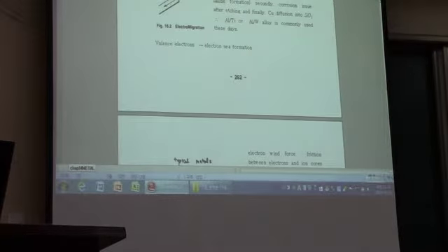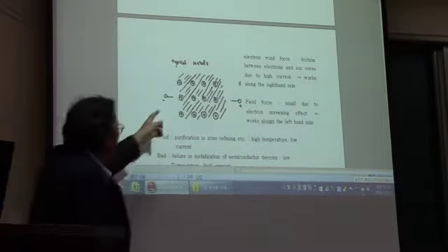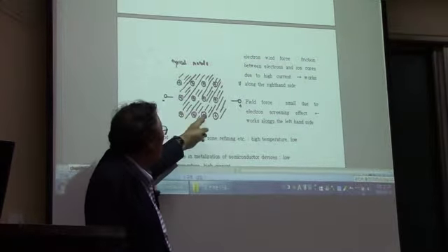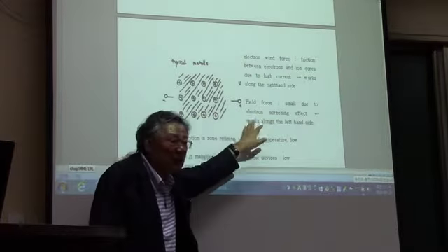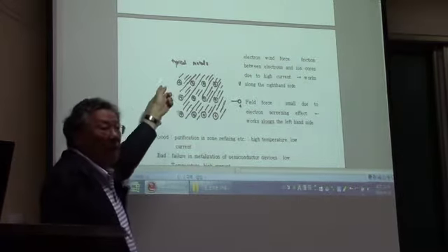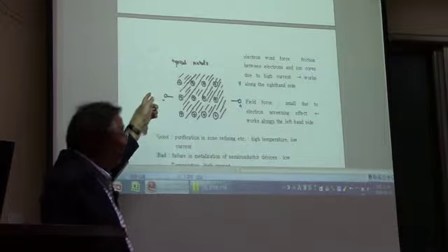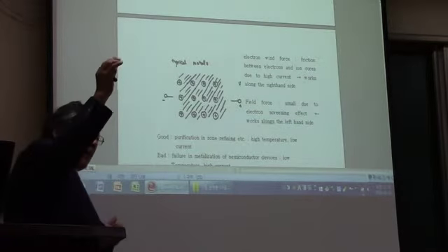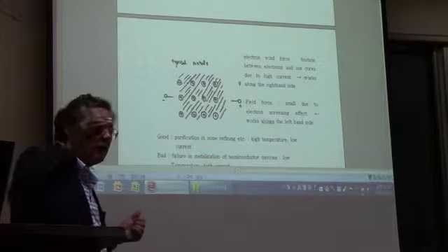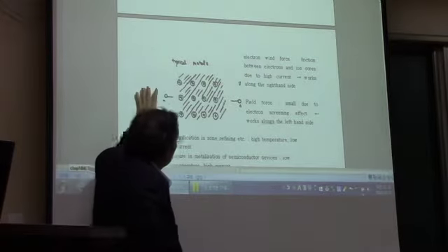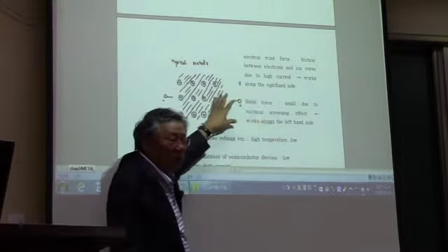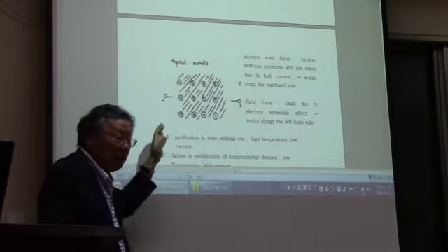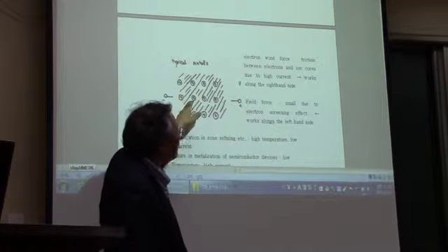So in a metal line, you're going to have aluminum ions like this, which are very sluggish. They're not moving at all. But if you have a DC current like this, at that high current density, even 100 or 1,000 times higher than the current at home, you're going to see the wind of electrons. Electrons are moving in one direction, and we call that wind.